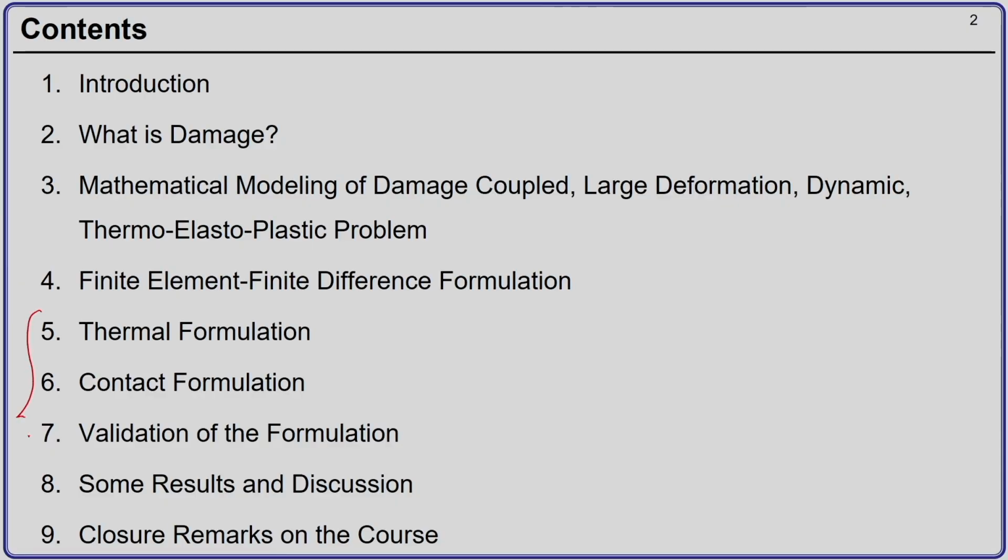So, welcome to this last lecture on finite element formulation of ductile fracture in coupled thermo-elastoplastic dynamic contact problem. In today's lecture, we will discuss the thermal formulation, the contact formulation, we will see some validation problems, finally, some results, and then we will conclude this course by discussing what we have covered and what we have not covered. So, in today's lecture, we are going to cover the following 5 topics.